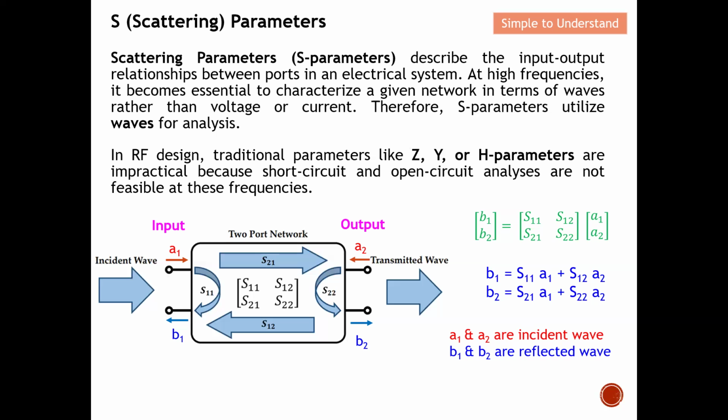At low frequency, it can be a short circuit. However, at high frequency, the inductor may not be a short circuit anymore. It becomes quite a significant reactance number. So therefore, at high frequency, I can't use an inductor to represent short circuit anymore.